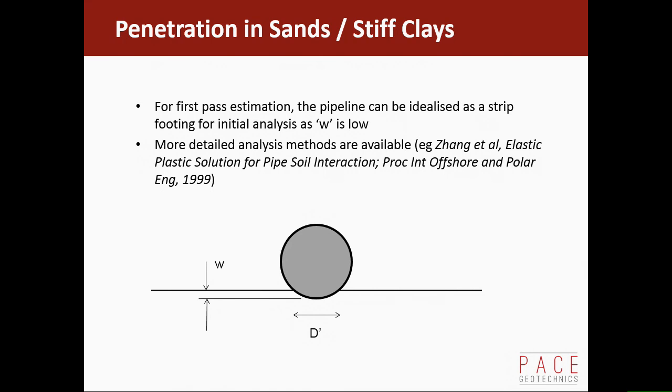Now, in harder soils, the pipeline penetration is very low. So that makes life easier because we can consider the contact length here as a simple strip footing. And then from that we can calculate W dash. Now I'll talk a little bit about foundation design tomorrow. Might even start that lecture today if I get a chance.